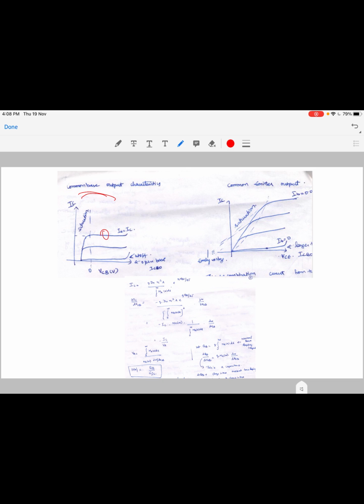So you have what is called a constant current characteristic, which is useful for current source kinds of applications. You have a second kind of device, which is called a common emitter case, where you have a strong change in the collector current with the collector emitter characteristics. You have three regions of operation. Basically, you have a cutoff region, a linear region, and a saturation region. And these regions are determined by how you bias individual junctions.